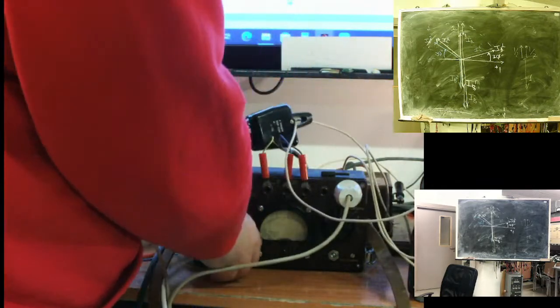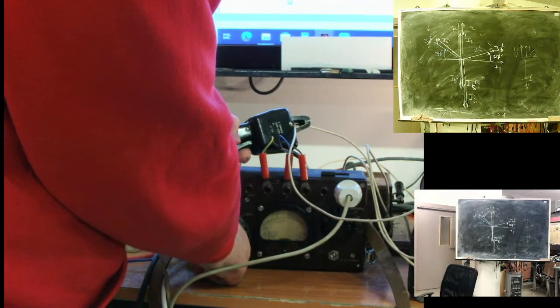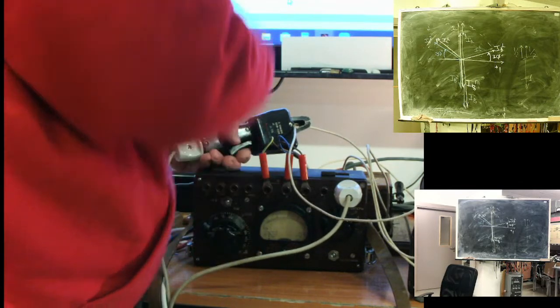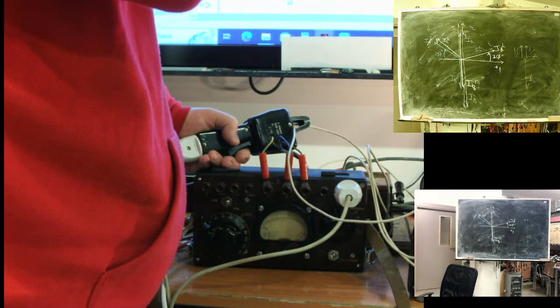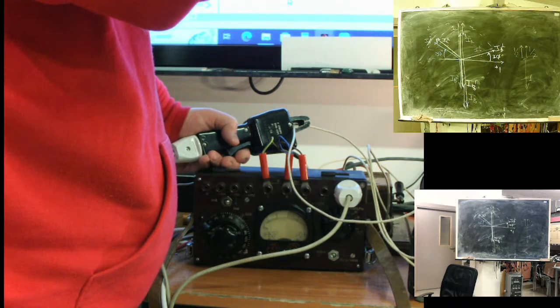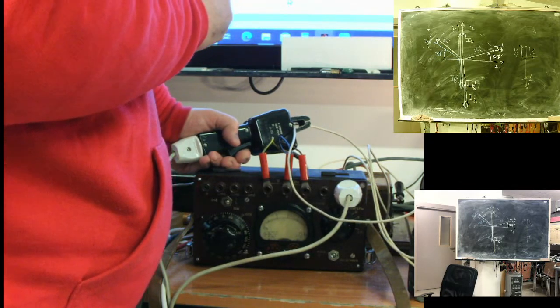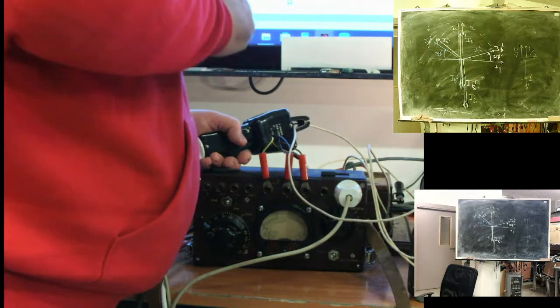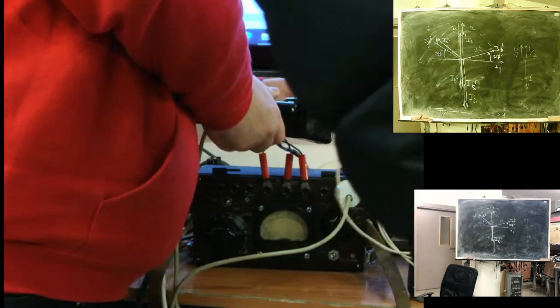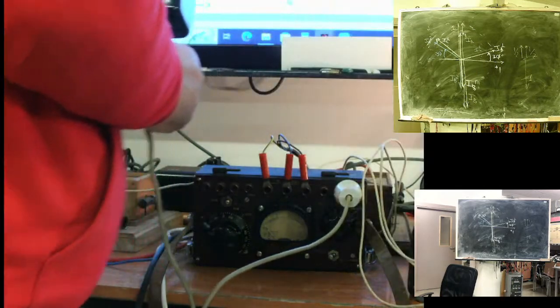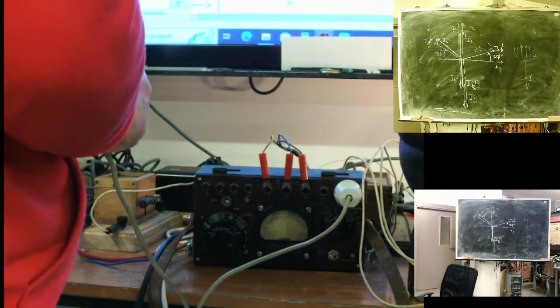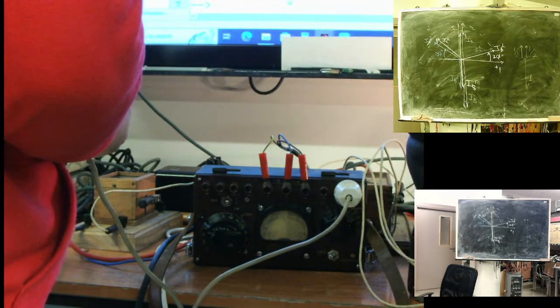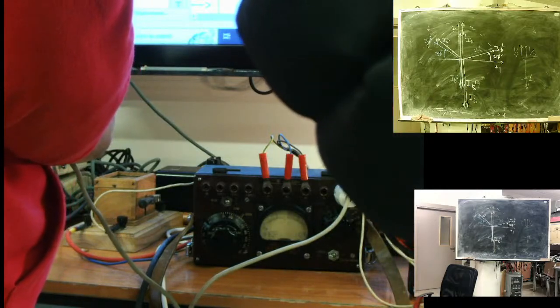And for C phase, 40 and leading. Oops, we have an opposite phase sequence. The angles are not as expected, we have an opposite phase sequence.